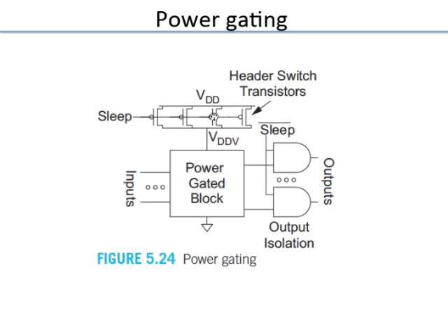Correct. So what will happen is, see, there is some capacitor, and you'll have leakage current going, right? It will start discharging this. There will always be some capacitor. So VDD V voltage will start falling. Eventually it can go all the way down to ground. When you turn it on, this has to charge up again, right? So you have to wait till it charges up before you can start using it because the voltage has not yet reached. So that is another thing. Going in, coming out, right? How long does it take?